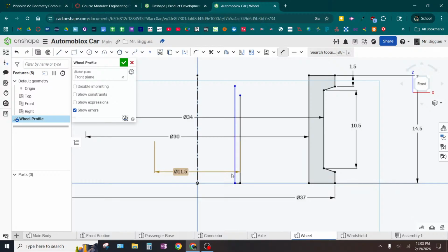For the inner, same technique. You can either grab around the wall and try and measure the thickness. That's not perfect. About 1, by the way. Or you can put the inner teeth, the teeth that are on the top, that are for measuring inner dimensions, and you push them apart as much as you can. I got about 8 or so doing that.